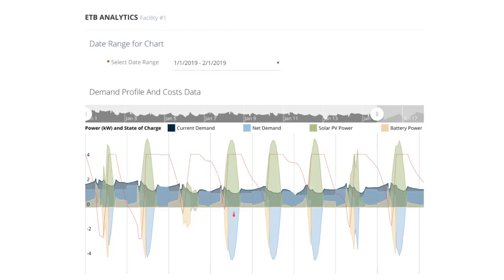We can see that the solar array is really too large. There's a lot of energy being exported to the grid, and so if we're in a situation where the outflow onto the grid does not have a lot of value, there's really no need for the solar array to be this large. Even half the size would be too large. It could be a third the size and still be reducing peak load during the middle of the day and providing enough energy to charge the battery.